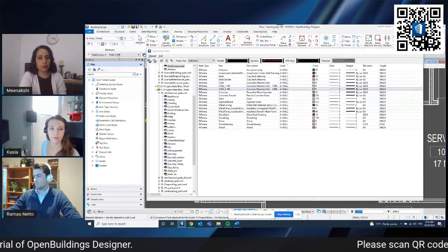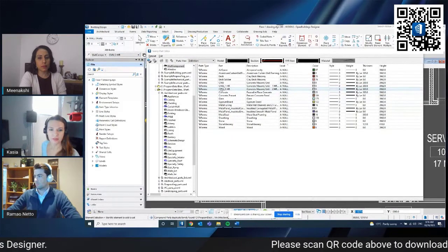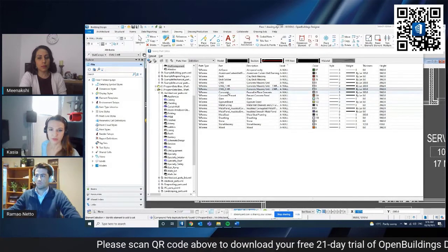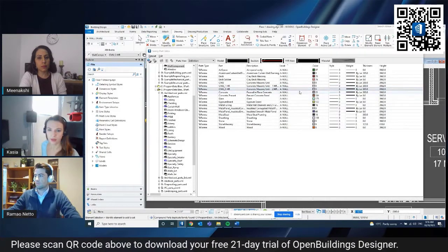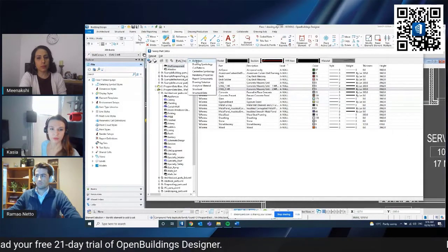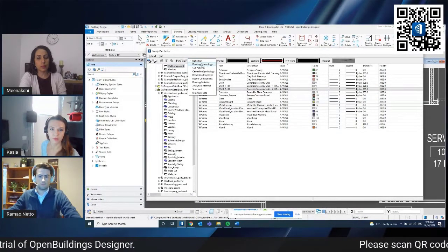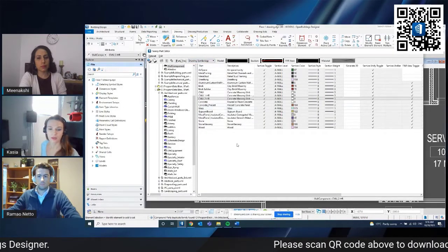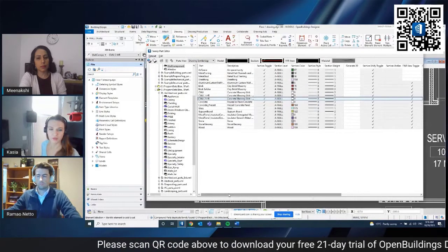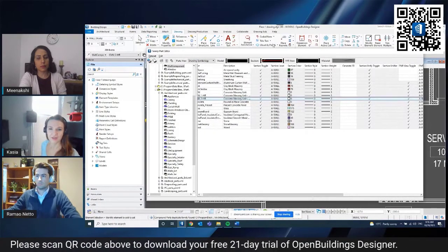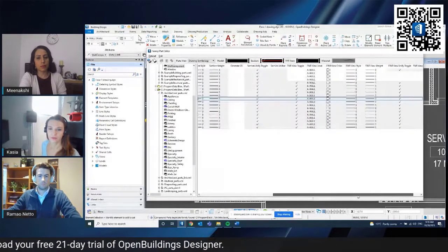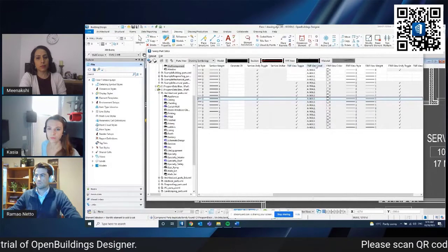So the part that I selected, the CMU wall with the fire rating of 2 hours, is now selected, and if I go in this parts view tab to the different mode, to drawing symbology, I can now control the attributes of these parts in section view, and further in the front and rear view.